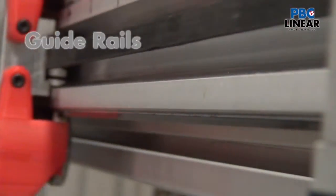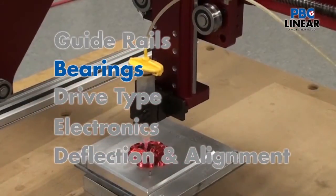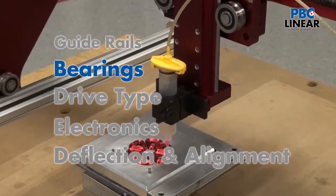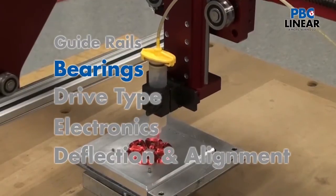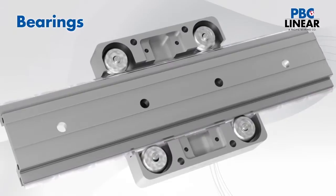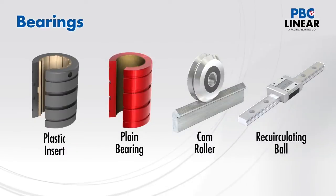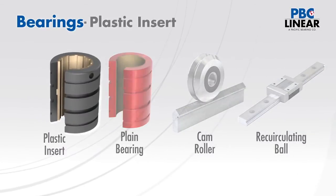Often there are factors such as contamination or the operating environment that will have a large impact on the final bearing selection. But whatever style is chosen, the bearings must be able to produce acceptable results within the given location range for an application. Usually this is related to the fit, or how the bearing or carriage feels on the rail. So let's look at the net effect of 4 different styles of bearing on accurate repeatability.